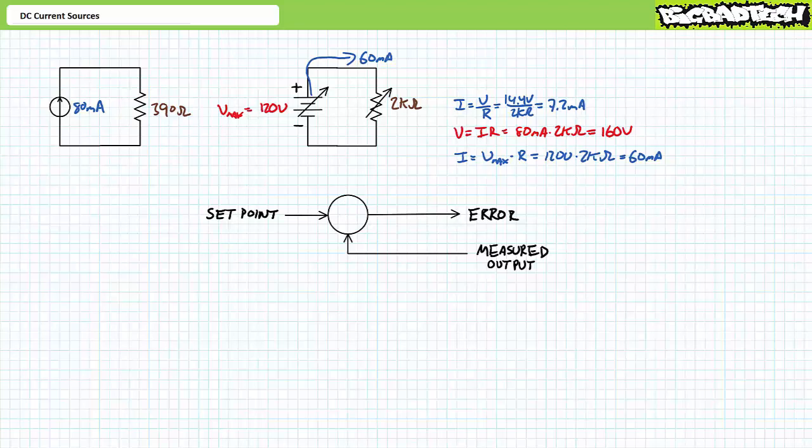Keep in mind we'll be seeing the current source again in later circuit analysis scenarios, as well as making use of a handy equivalency between current source and voltage source configurations called source conversion. Remember, never place current sources of different magnitudes in series with one another, and current sources in parallel add up. Stay on the right side of Kirchhoff's laws. Believe me, the judgments are swift and the punishments are harsh.